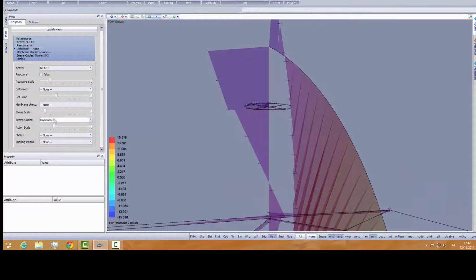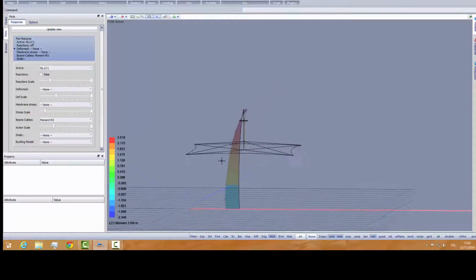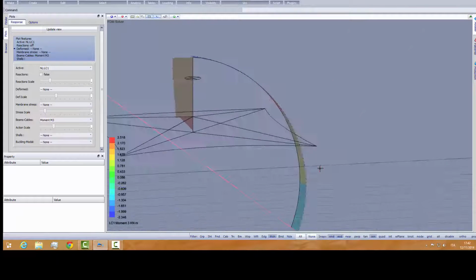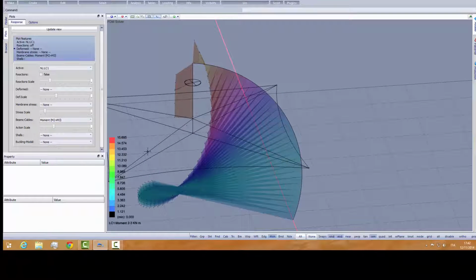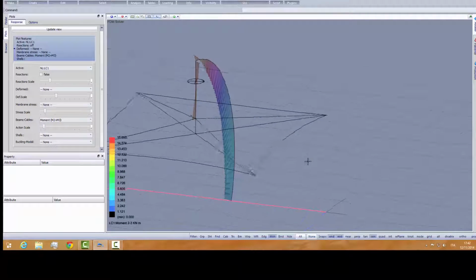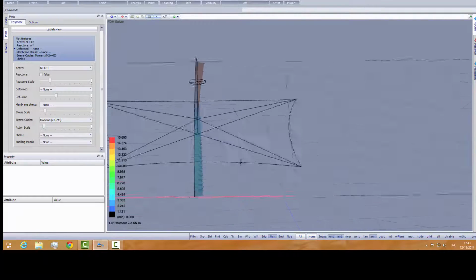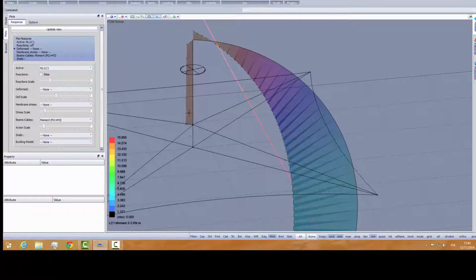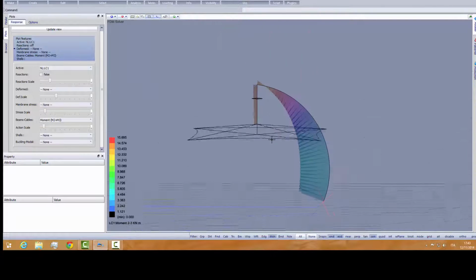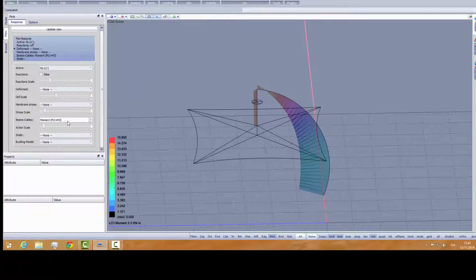These are bending moments on the second axis and bending moments on the third axis. So you see that we can also activate bending moment M2, M3. Let's scale it a little bit down. And this is a three-dimensional bending moment. And we see that the main moments are on the center of this, the center pole, and of course on the main pole.